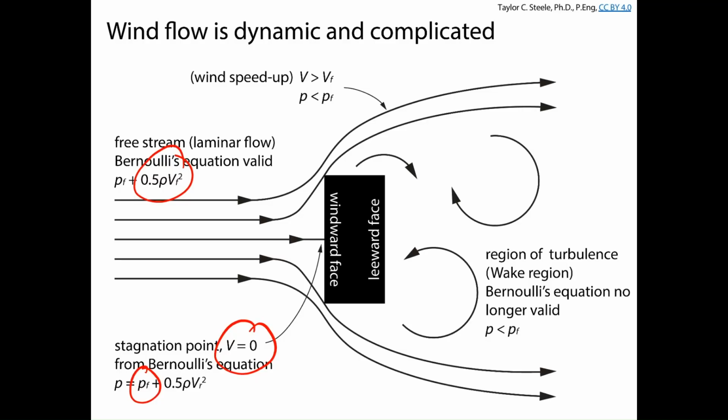There he goes. Anyway, the stuff that goes on the other sides of the structure is quite complicated. Basically, because there's a blockage here, we're preventing the flow of the air across the complete volume of space that the wind is blowing toward. So as the wind tries to go around the structure, the area of flow is reduced, and so the velocity increases, right? That's a concept you learn in fluid mechanics. The velocity increases, so it's quite high, and the velocity of air inside the structure is technically zero, right?